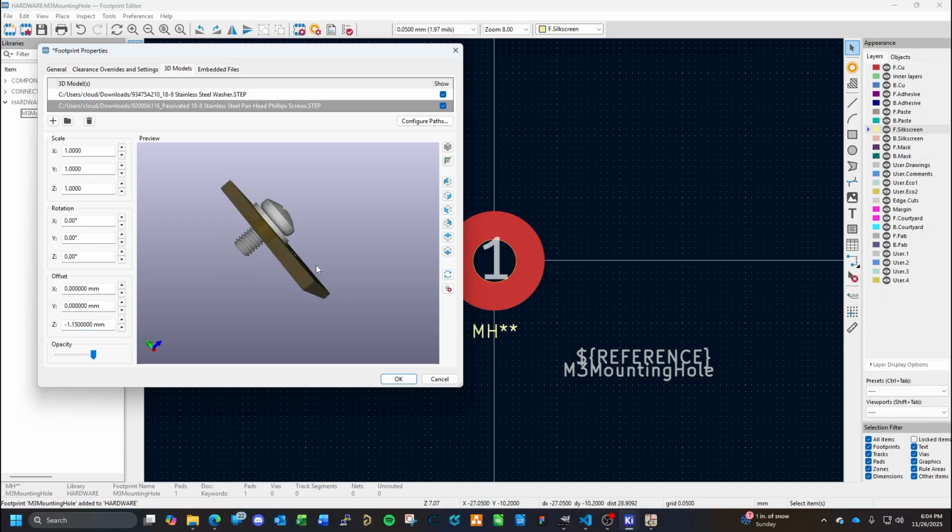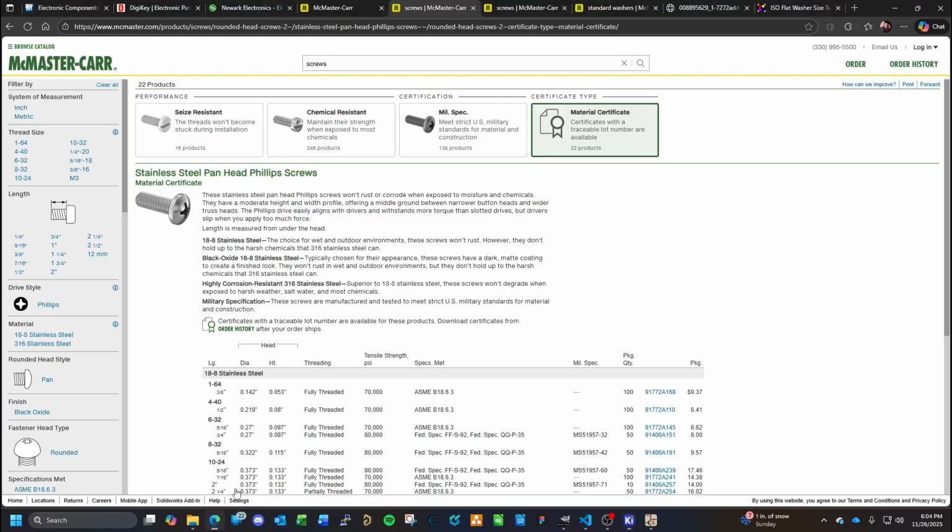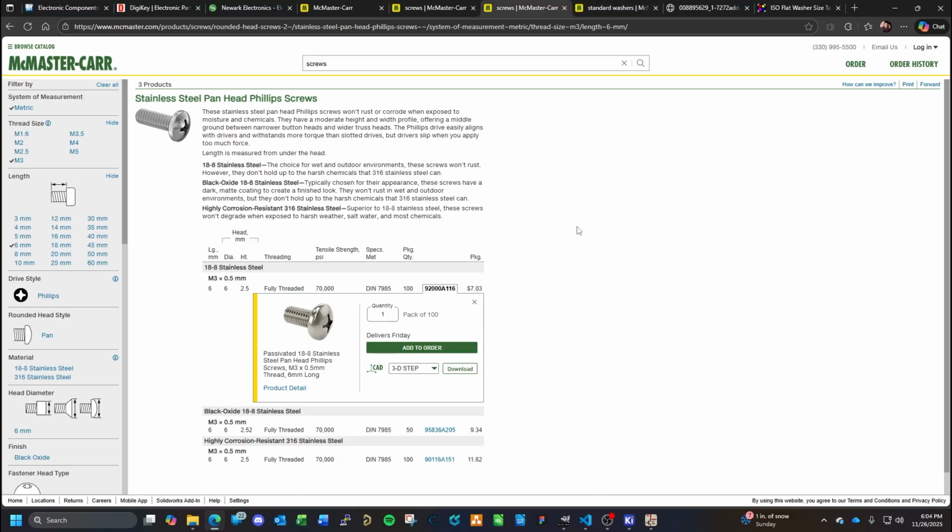And not to be perfect again. So what's nice about this, I chose I think it was a 6mm screw. That's another great thing about companies like McMaster-Carr and all them, is the availability of 3D files for engineering purposes. What's great about Fusion is you can download straight from McMaster-Carr for your designs. You can actually go pull up the catalog in Fusion, if I remember, I haven't done it in a while, and actually download the STEP files for their products. So when you're actually doing enclosure design, you can have everything from their site.